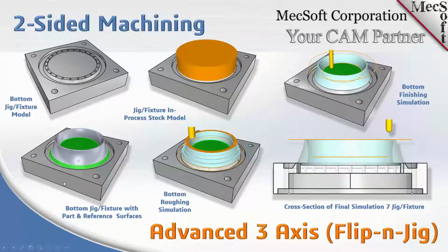But down here on the left side bottom view, you see that we have the fixture with the part on top of the fixture. Now this is not the cut material simulation. This is the actual part model in the CAD file. So when we machine the top side, we have another flat surface shown in green, which is positioned below the quadrant area on the inside to catch the tool.